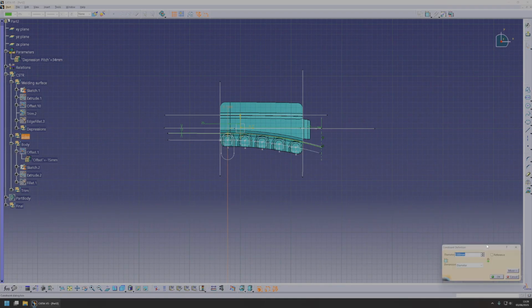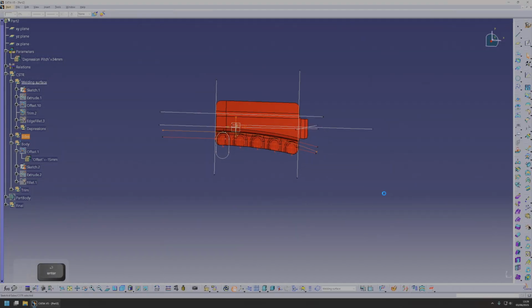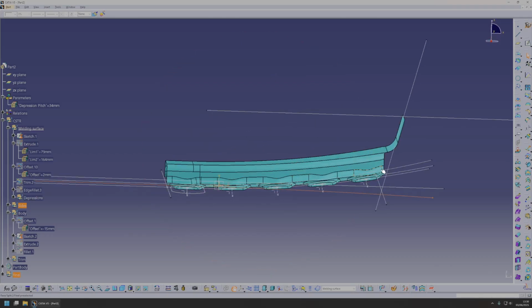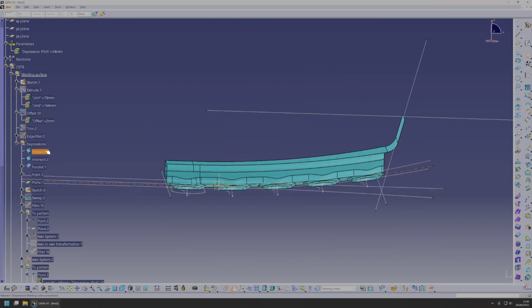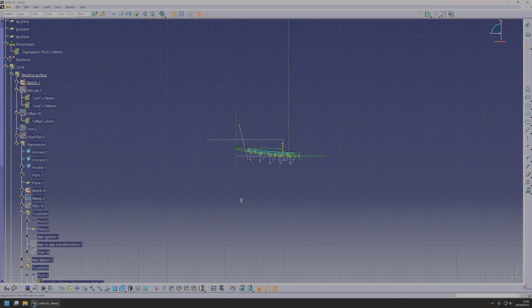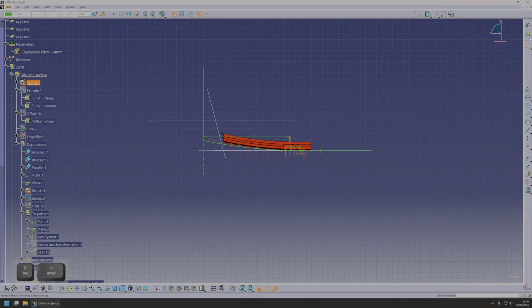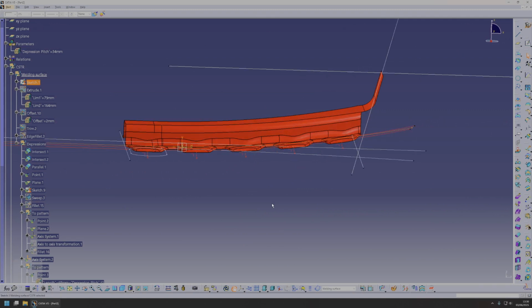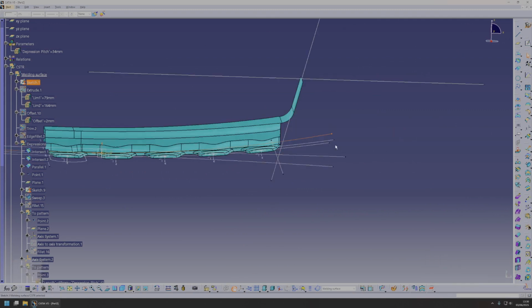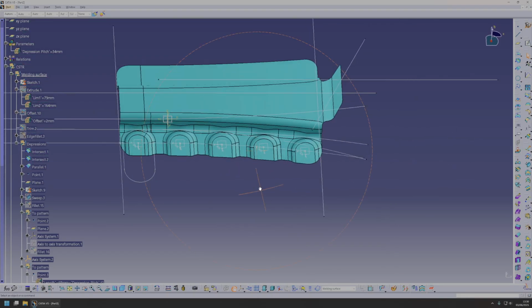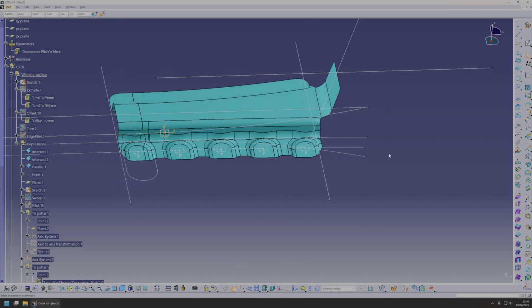Let's say we don't like this, we want a smaller radius here, like that. Let's say you want to change this curvature, that should work as well. So you have the welding surface here, want to make it more flat, not an issue. And these depressions will just automatically update and keep their pitch and use the other surfaces as a base.